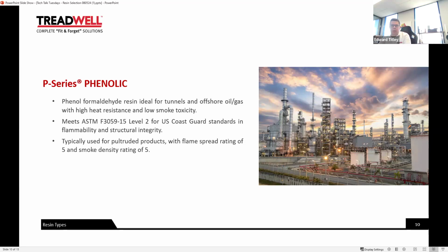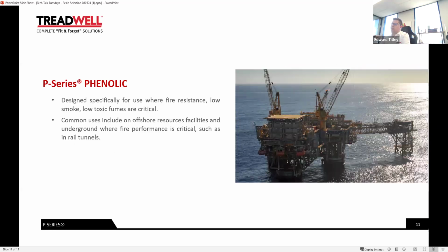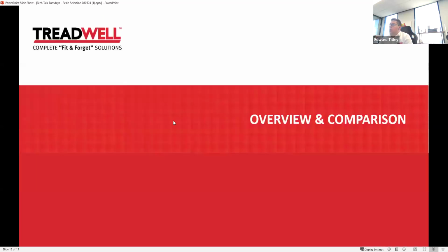By way of example, if we say that an I series product is $1, then a V series product will be about $1.25 or $1.30. P series will be in the order of $4 to $5. So it's a reasonable cost increase. And that's why I'd say it's not a commonly used item, but it is necessary in some applications. As we mentioned, the common uses for the P series product are underground, where fire performance is critical, and offshore facilities.